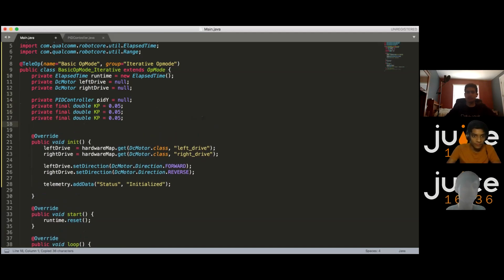These are just the values that we actually used for our Y movement PID for our mechanical drivetrain for Skystone. You see we have our large KP, smaller KI, and then an even smaller KD. In our real usage, we didn't use KD, but we just wanted to show what an example value would be for KD.